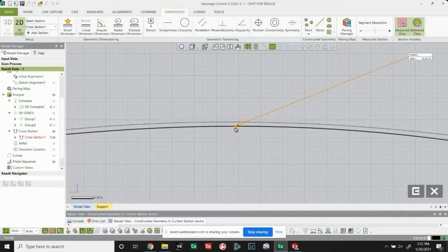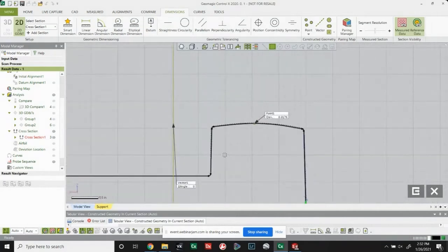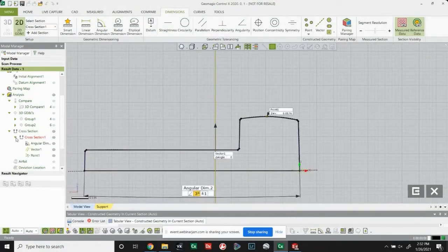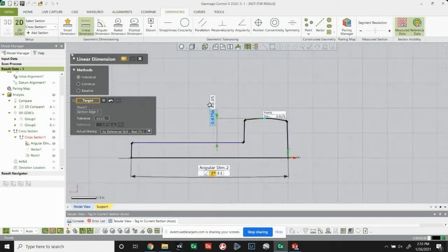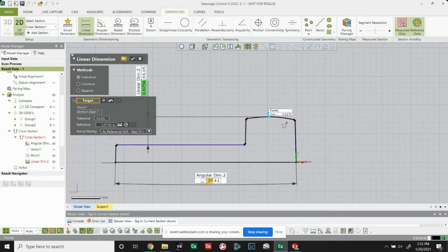If I hover over the point, it shows me the nominal point as well as the projected point. You can see it's up there, just to the right. That's the highest point on the real part in that section. What's very cool is that with a little bit of creativity, I found a way to take that point very quickly and accurately. So now this will be an extremely accurate measurement to that point, and that's repeatable, part to part to part. It's going to pull that same exact point from wherever that high point happens to be.